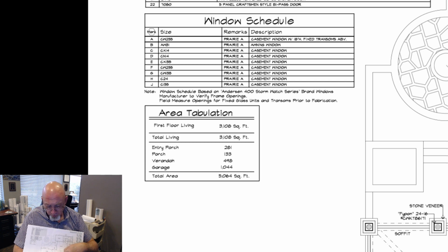A lot of times people say, "Well, it says 3,000, but I only came up with 2,600 square feet." But if you took each individual room and just the net wall area, yeah, you would get a much lesser square footage. But we always include, which is pretty much an accepted standard, the gross floor area, which is inclusive of the wall thicknesses, and that's how we determine that.